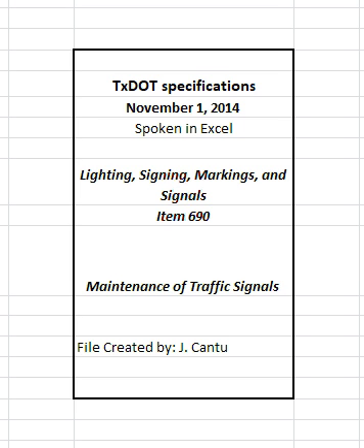4.1 Conduit. Install, replace, remove, or modify conduits in accordance with Item 618, conduit, as shown on the plans, or as directed. Use 90° sweep type elbow on conduits entering a ground box. 4.2 Foundations. Install, replace, or remove foundations for traffic signal pole, pedestal pole, and ground mount controller cabinets in accordance with Item 416, drilled shaft foundations, and in accordance with Item 656, foundations for traffic control devices, as shown on the plans, or as directed.